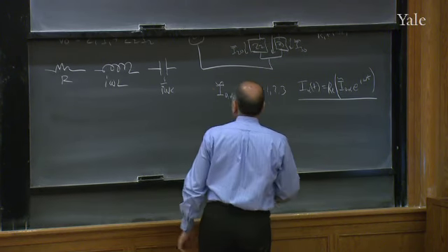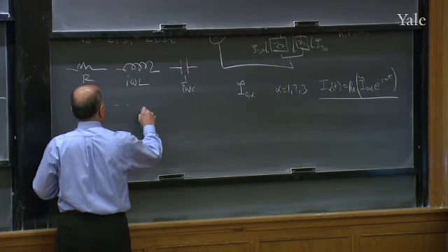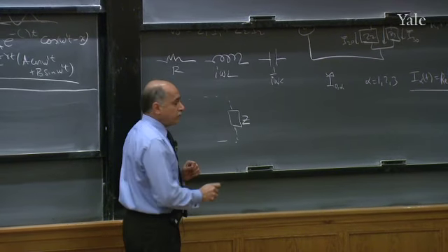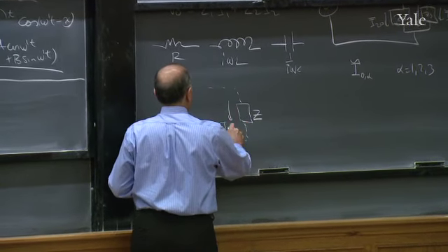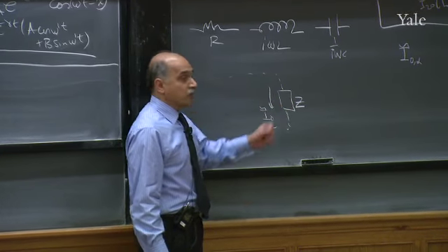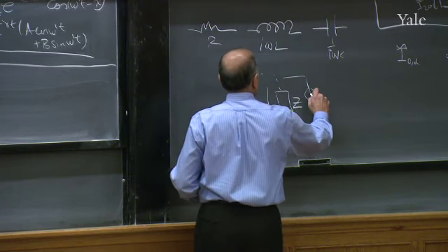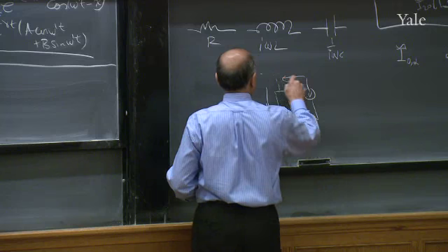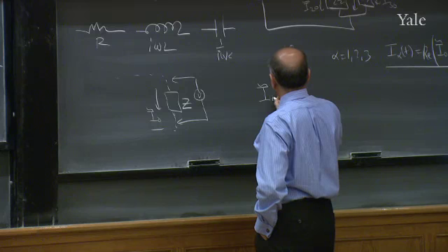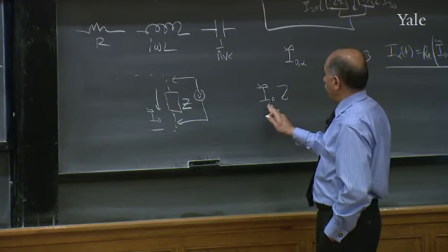How about the following? You've solved a very complicated circuit. I don't even know what's going on. Here is one guy. Okay, it's part of a big mess. Its impedance is Z. There is a current I twiddle 0 going through it, meaning that's the complex amplitude. If I ask you, what is the actual voltage across this? If I put a voltmeter here, what will I measure? The answer will be, again, I twiddle 0 times Z. That's the fake Ohm's law calculation.